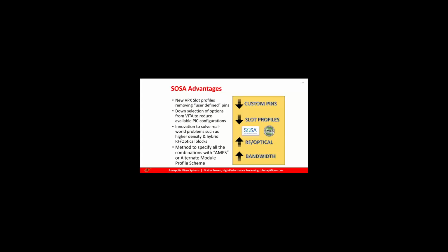So OpenVPX had a lot of user pins, and that basically meant custom pins. Modules that go into OpenVPX systems often have a few pins that are custom. That means that a lot of these standardized VPX systems actually have custom plug-in cards and custom backplanes. So SOSA defines all of those pins.